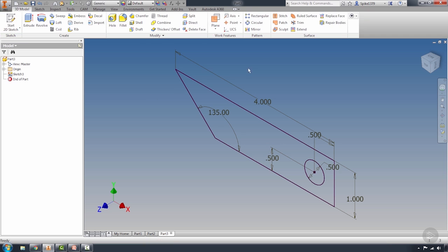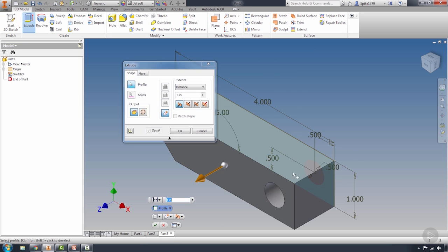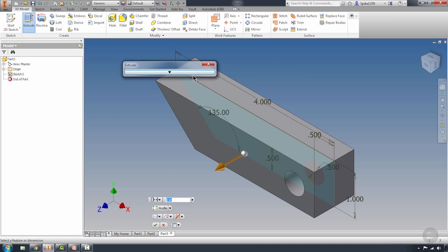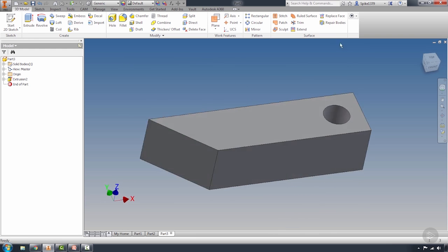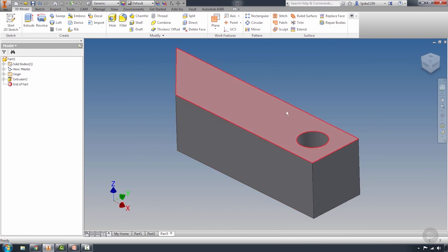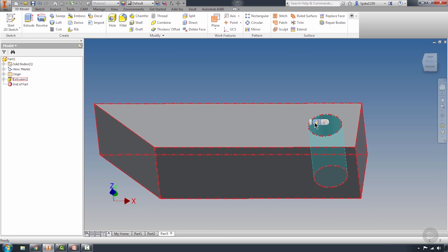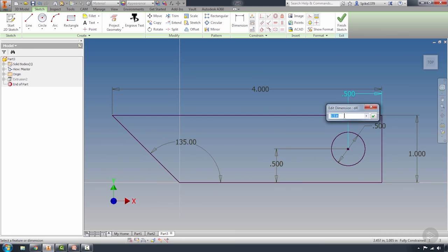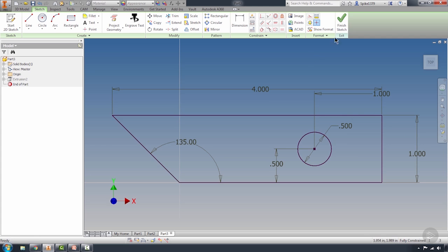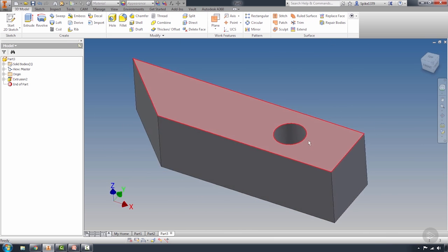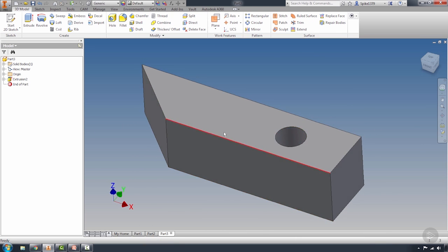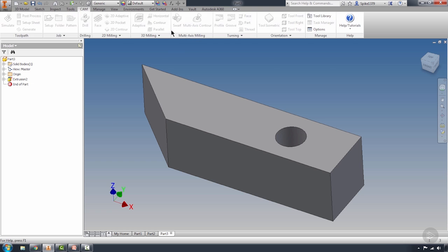Now I'm going to finish this sketch, and we're just going to simply extrude this portion of it, and I'll leave it at 1 inch so that I have a solid. Now it also means that in parametric design, if I change one of these features, I can quickly edit, say, the sketch environment here, change this to 1 inch, and the rest of the design will update, including the solid. So you no longer have a disassociation between the solid or any of the geometry that's going to control our CAM process. And I'll jump over to CAM real fast.